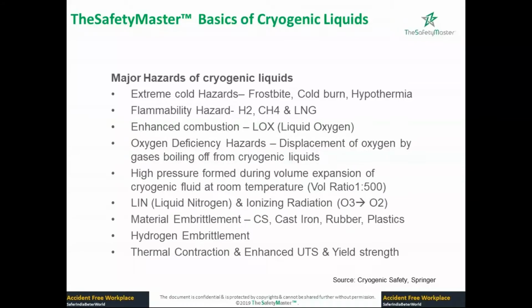And then we'll look into the oxygen deficiency hazard, which is specifically for when you're dealing with inert gases like nitrogen, argon, even hydrogen. When you're dealing with liquid nitrogen or liquid argon or liquid carbon dioxide, the vapor displaces the oxygen by boiling off from the cryogenic liquids. So this vapor, like liquid nitrogen vapor, will displace oxygen, and you will end up in a situation where there's an oxygen deficiency in the room or in that particular area.